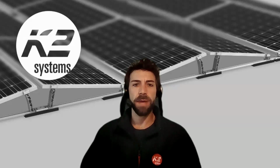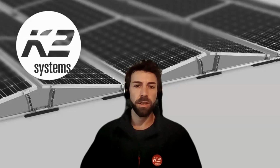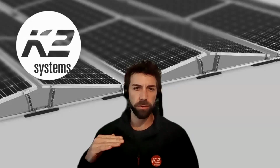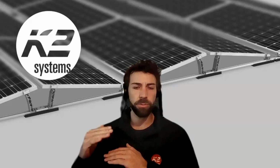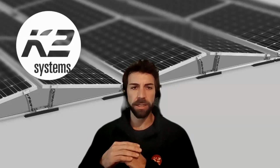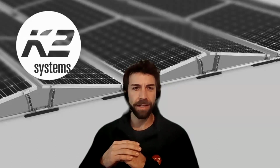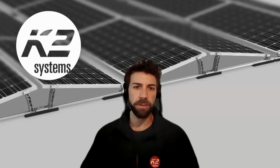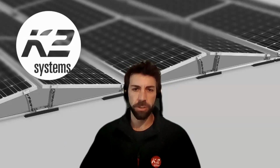Obviously, the more space you get in between the surface of the roof and the bottom part of your module, it's getting higher if you put a 25 centimeter stone, but you will also need more ballast. There is a value which is calculated in, it's a factor. So the higher you go, and I think it starts from 120 millimeters, so if your stone is higher than 12 centimeter, you will get higher ballast values. Just to keep that in mind too.